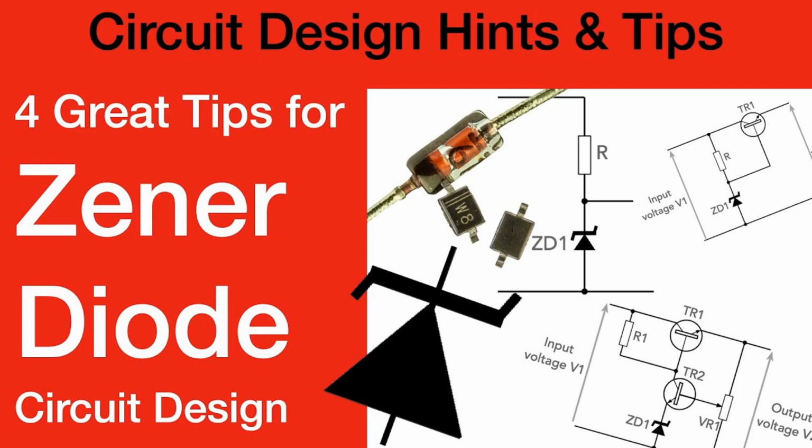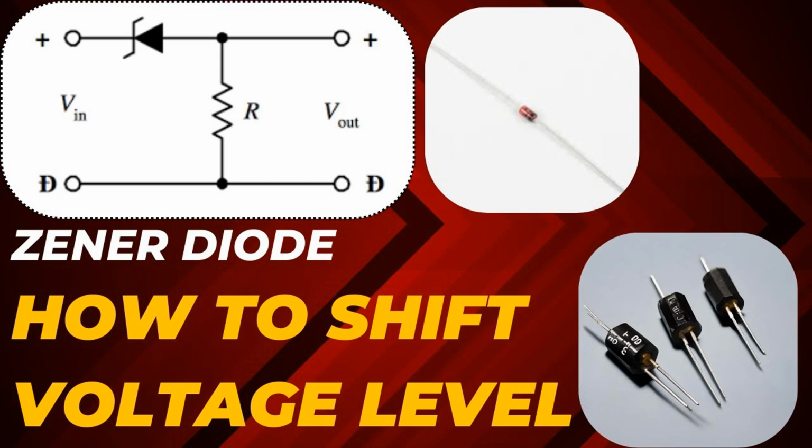3. Signal clipping circuit. Components: Two Zener diodes, VZ equals 5.1 V. AC signal source. Circuit description: Two Zener diodes are connected in series, but in opposite polarity across the signal source. The diodes clip the positive and negative peaks of the AC signal to plus or minus 5.1 V.